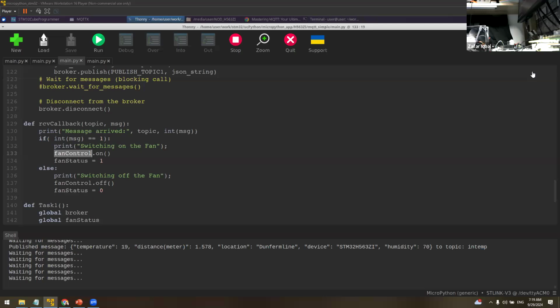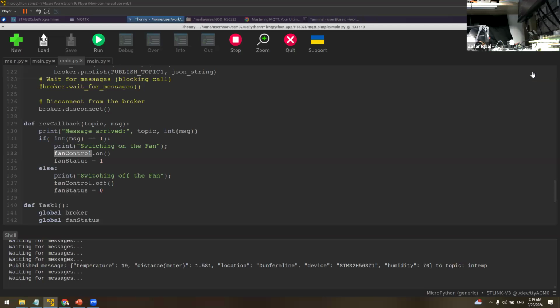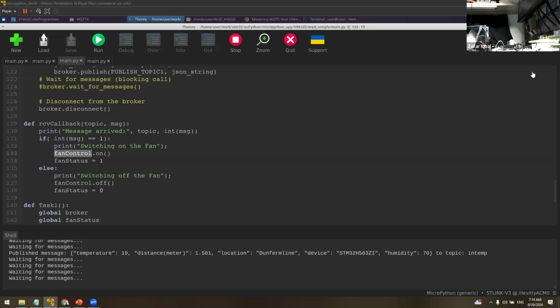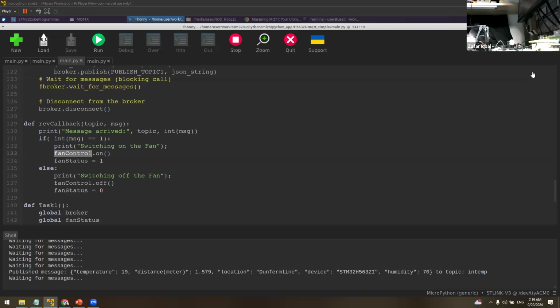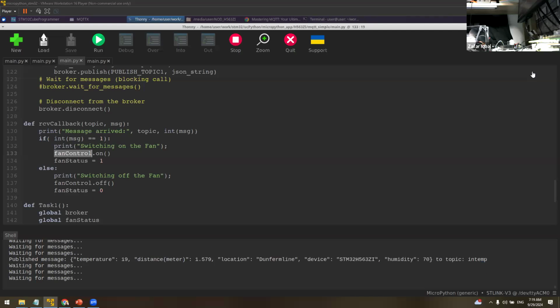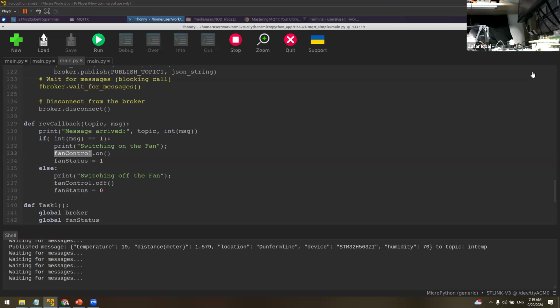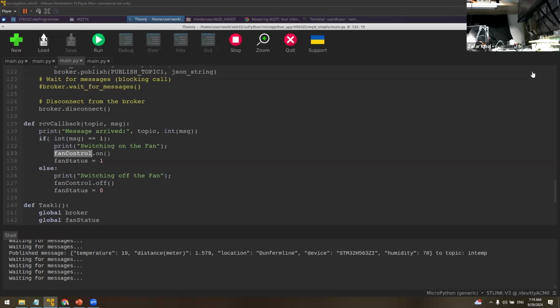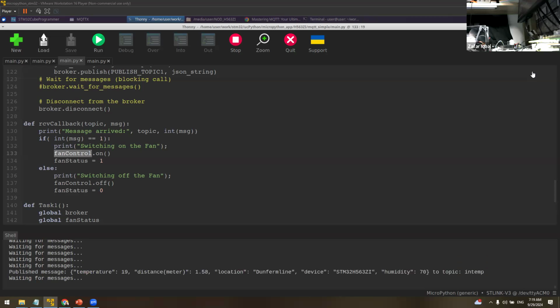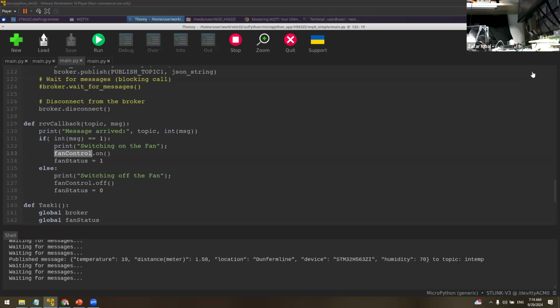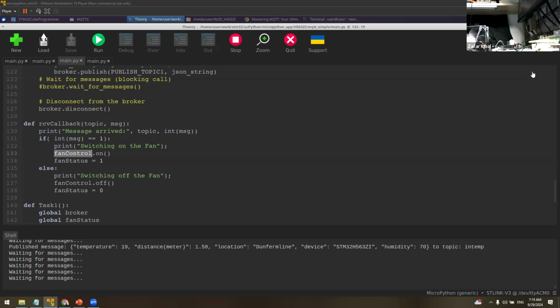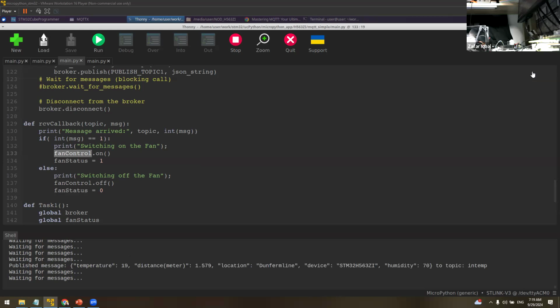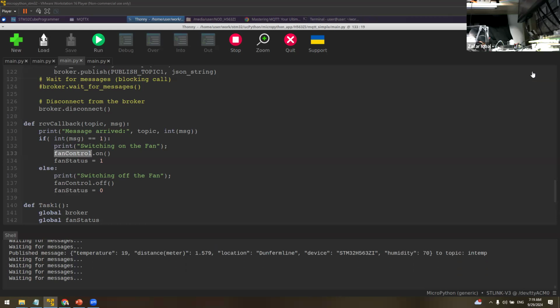At the inlet, it keeps on monitoring the pressure inside the pipe. So suppose someone breaks the pipe and the oil is getting leaked, then what will happen? Both sides of the sectionalized valve, which is 25 kilometers apart, will sense that there is a drop in pressure.